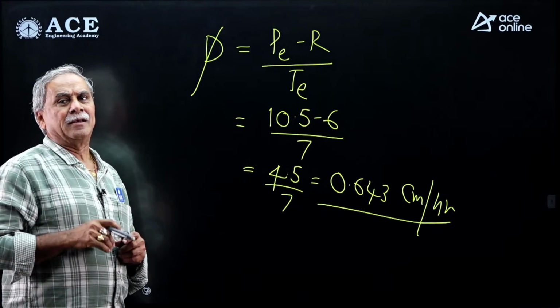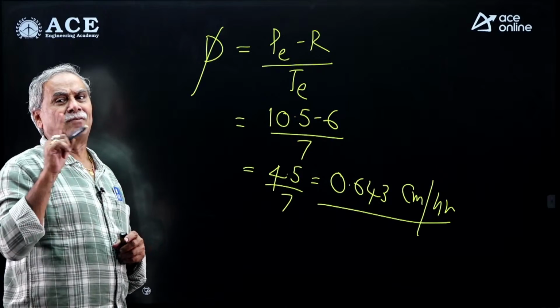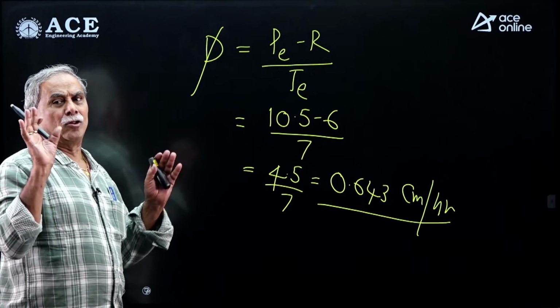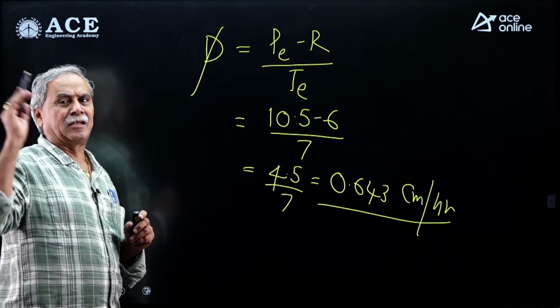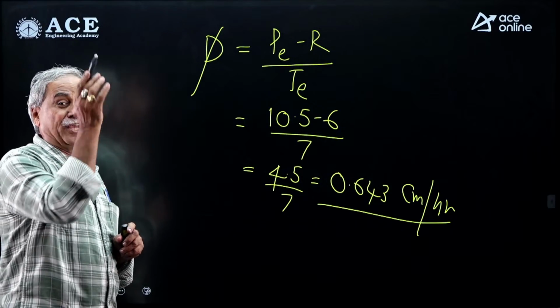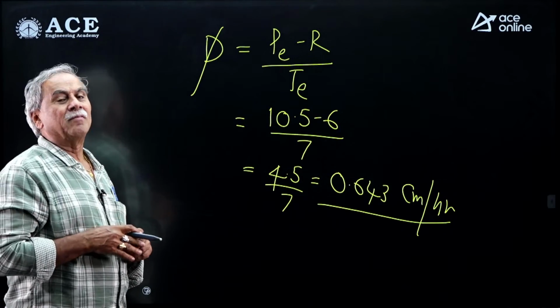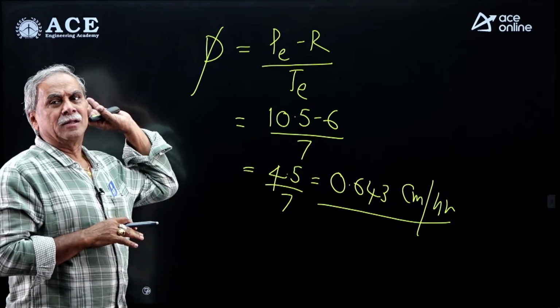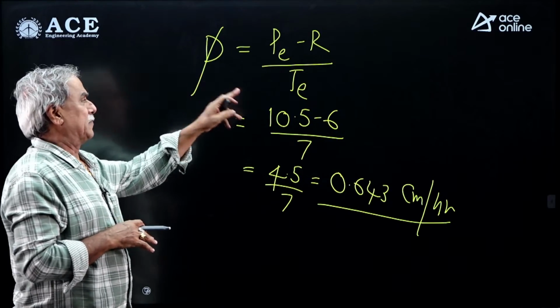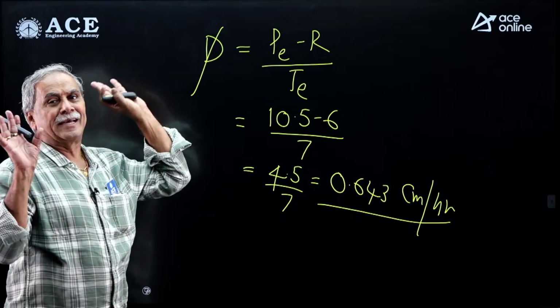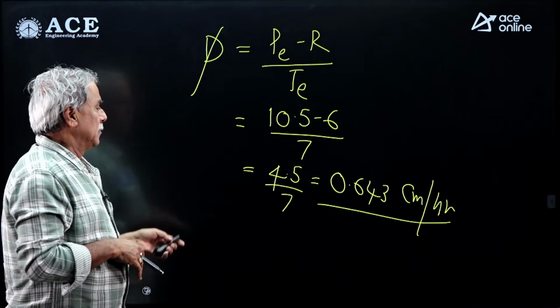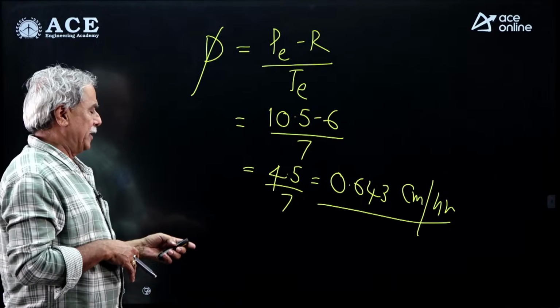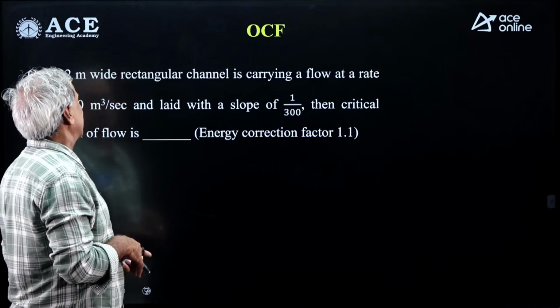Check the procedure. Calculate the independent rainfalls in every 1 hour. Get the value of W index, P minus R minus initial losses, divided by total time of rainfall. Compare each I value with W. Wherever there is effective rainfall, that is I value more than W, take them as effective rainfall. Get phi index. Standard model, and the answer is 0.643. Let us go to the next question.